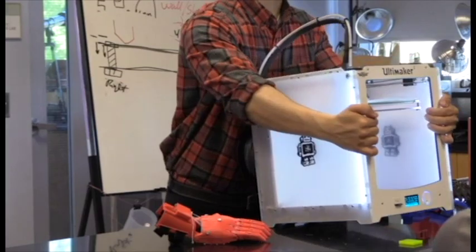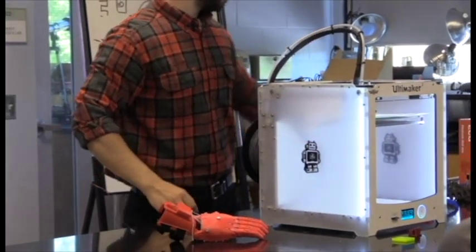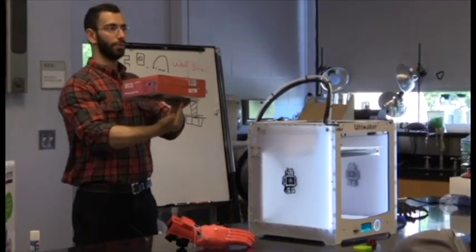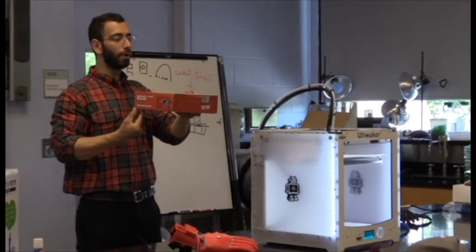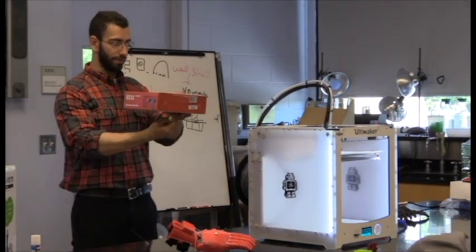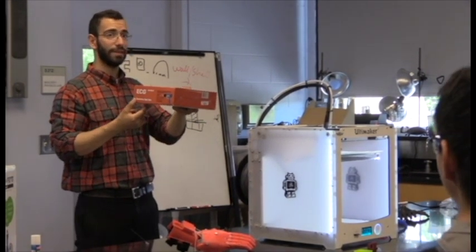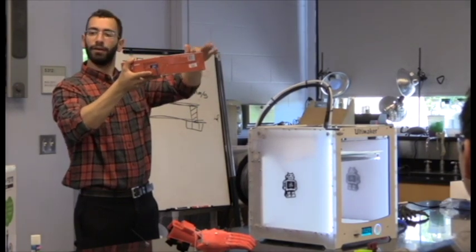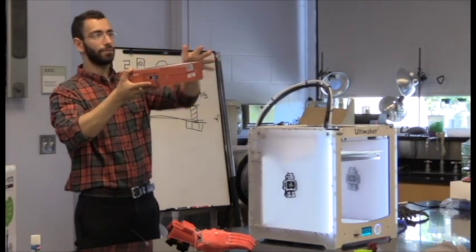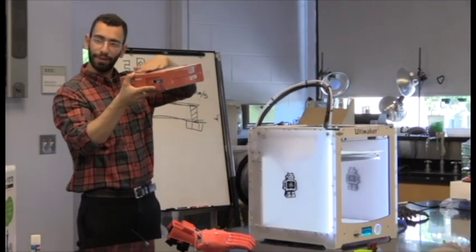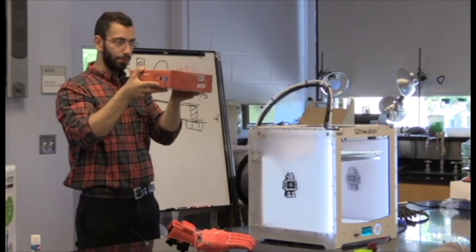And now just so you know one thing. If the bed looks like this guy, right? It's flat, and they have three screws. If you move one of them, you might want to do this process more than once, because think about it. Once you pull one, this guy up here went up. It's one flat surface, a plane. You can't pull in one area without something happening to the other one. Okay, it's flat.